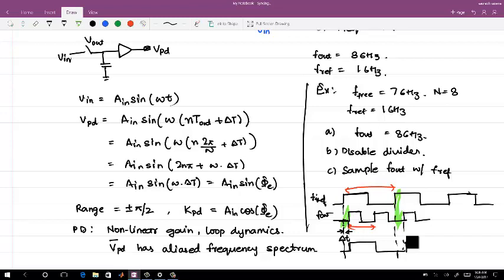Frequency or phase error? A type 1 PLL cannot correct for frequency error beyond a certain limit. There will be a finite phase offset.